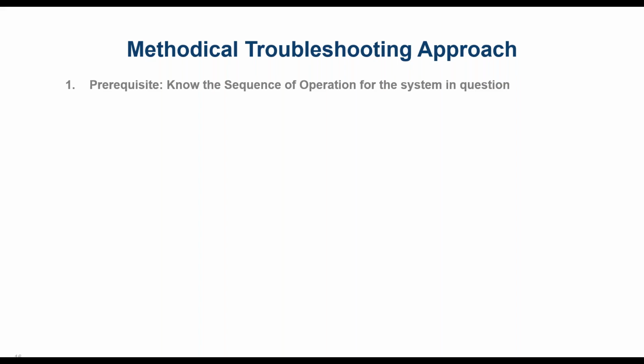All right, and now before you send a technician out to physically go to the space or to the location of the system to investigate, you should probably pull up the BAS first, because if you pull up the building automation system first, it'll help you narrow in on what the root cause is. Maybe you'll be able to figure out what the root cause is just by looking at the automation system. Or if anything, you'll be able to narrow it down to just 1 or 2 items before you send out a technician. And you're going to be much more effective at troubleshooting systems if you utilize your building automation system first and foremost before just blindly walking into a space trying to figure out what's going on.